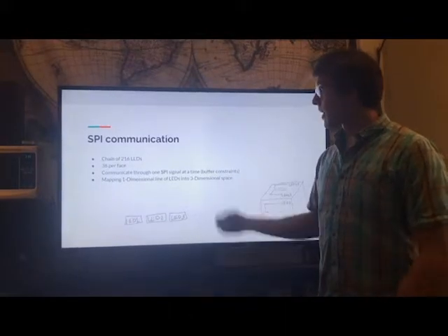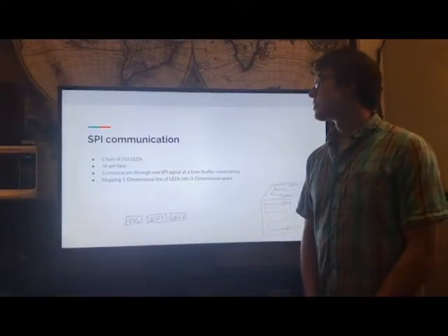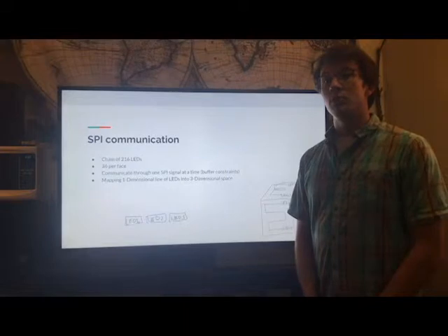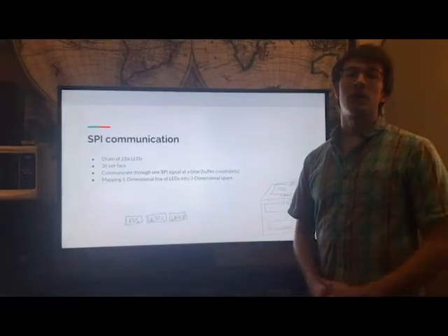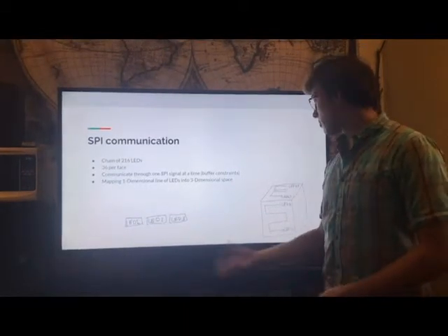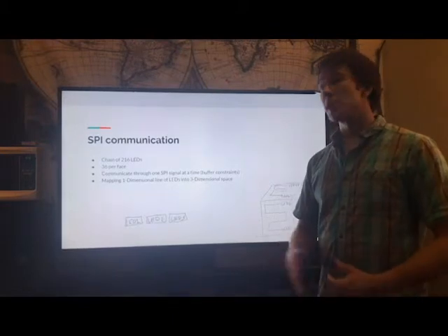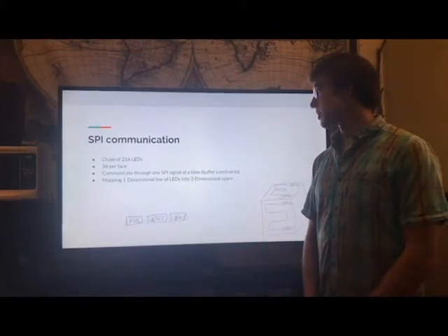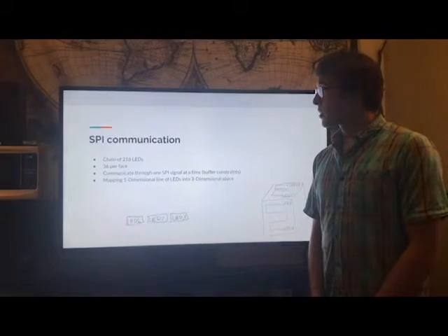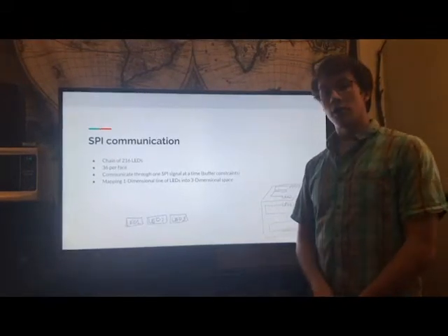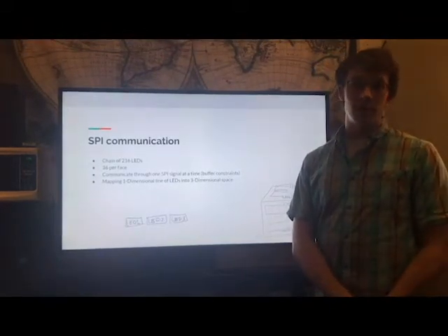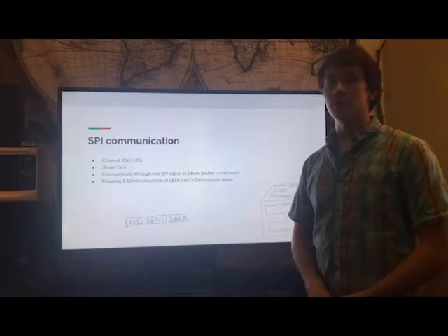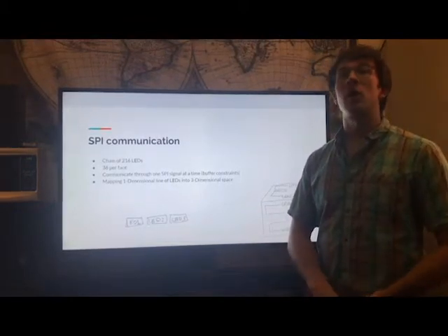You can only send 1 byte at a time due to buffer constraints, so we use polling to wait for the flags to be set based on when the LED was ready to process the next byte of data to send all this data to the 216 LEDs. To save on memory, we made the LEDs either off or a consistent value so that we only needed to keep track of the state of whether an LED was on and off and not a particular color.